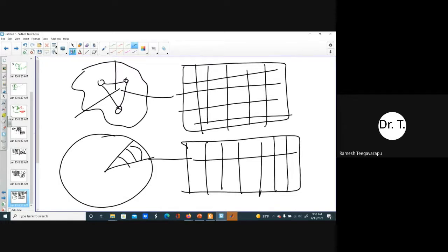So I would definitely prefer the radar product if it is available in your region. I would prefer that one for distributed hydrologic models compared to lumped, rain gauge-based calculations. So I know it's a long answer, but I just want to convey the problems associated with both types of data sets.